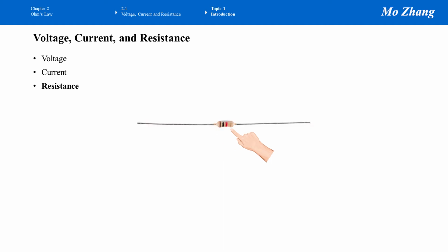So we flip this resistor. The 4th band is the gold band. The resistor is in the correct orientation. The first color band is brown, the second one is black, and then we have red, and the last one is gold.